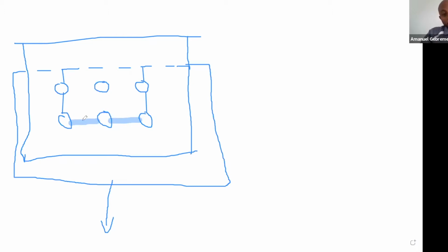Now, when you check for this type of limit state, the capacity is in many cases much lower than when you check the previous limit states that I described, which were yield across the whole plate or tension through the net area. And this is particularly interesting because this is not the only block shear limit state that I have for this configuration. So for instance, it's quite possible that I could have a block shear limit state, let's see, of this type.